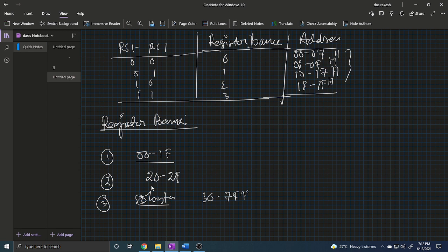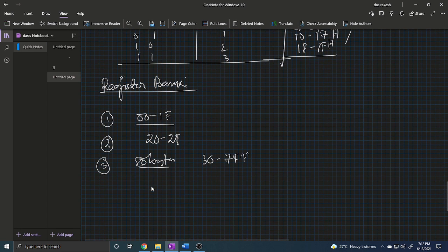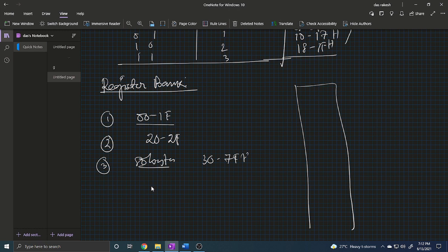These 80 locations of RAM are widely used for storing data and parameters, defined by 8051 programmers. Now we see all the RAM allocation of the 8051. This diagram is very important, because depending on it we can write our program.